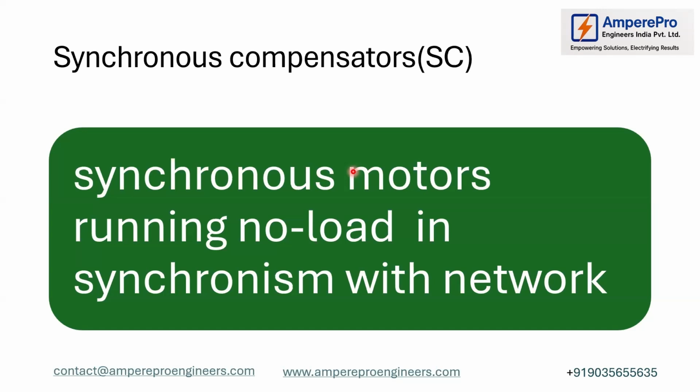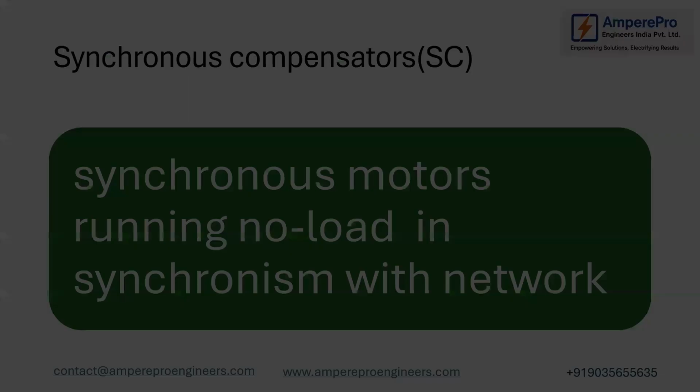To give this reactive power support, utilities and companies are adding something called a synchronous condenser, which is nothing but your synchronous motor. It will be connected to the grid and will act as reactive power support to the grid. So this is one thing.